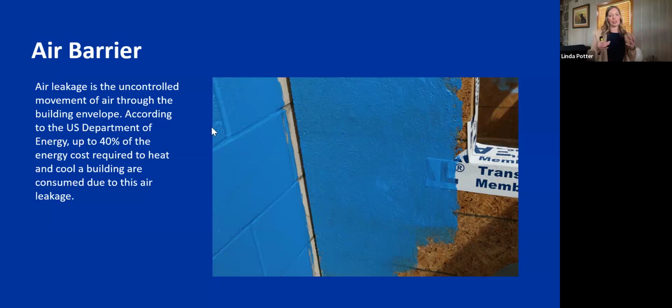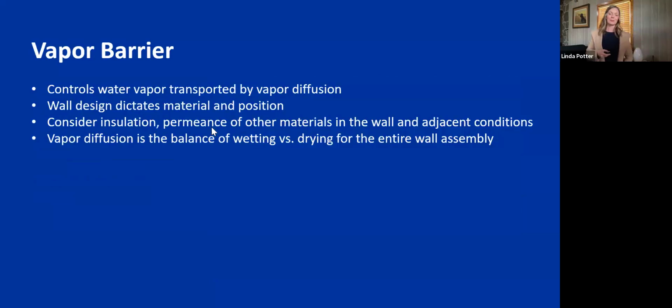And I'm not doing an air barrier seminar here, but I think it's important for us to recognize, if we care about thermal efficiency, as the title suggests, we care about air barriers in the building envelope. And if we care about the air barrier, we care about every penetration through that air barrier and how that impacts the building envelope and its air leakage potential.